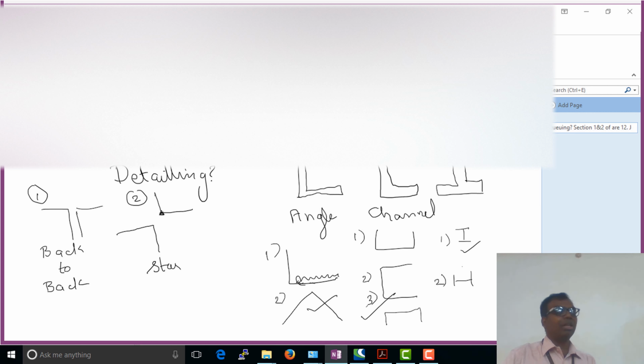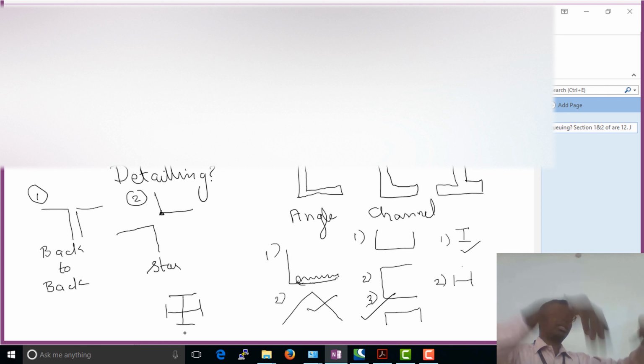Okay, so we've got very complicated base plates. Base plates are the place where the column meets the pedestal. Okay, so for instance, we've got this section, called a cruciform section. Two I beams are made to sit like this. Now when you look at the base plate, it will accumulate water and store it like a water tank. So we will definitely need to drill some holes to drain the water.